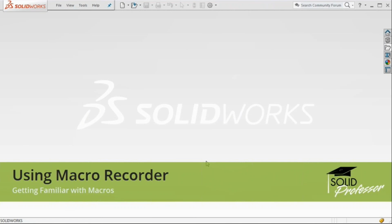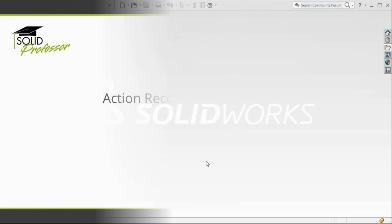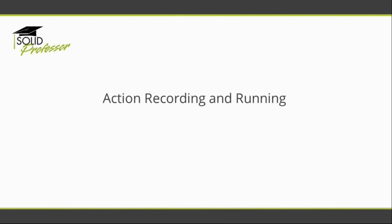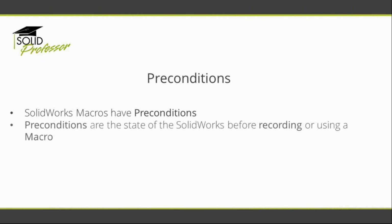In this lesson, we're going to learn how to record actions and run them inside SOLIDWORKS. We will automate together the process of creating a cylinder in an empty part document. Now, before we begin recording, I'd like to draw your attention to something important. SOLIDWORKS macros have what we call preconditions. They're basically the state of your SOLIDWORKS before recording or using a macro. In our case, we will take an empty part document as our initial starting point.